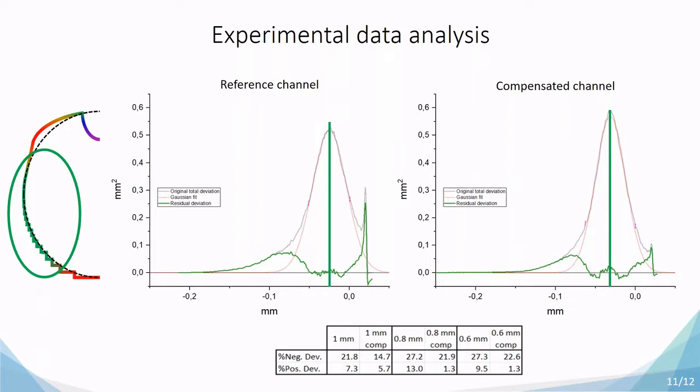This is not surprising because the offsets were calculated on sandblasted geometries, while these channels were analyzed as built. So the internal surface is covered in sintered powder, which is not removed, and therefore it's obvious that the final diameter measured with the CT scan is slightly smaller than the CAD one.